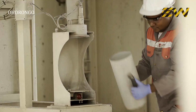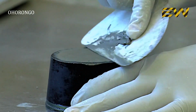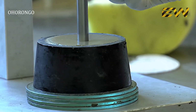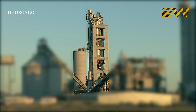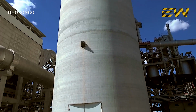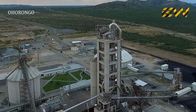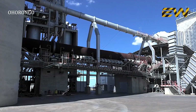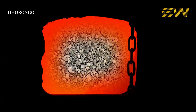The raw mix is tested once again to ensure that the chemical composition is correct in terms of the quality directives. Once the raw mix has passed the tests in the laboratory, it is conveyed to the preheater. The raw mill silo has a capacity to store 7,000 tons of raw mixture powder. Once the raw material has been processed in the preheater, it enters the 54 meters long rotary kiln, where the material is burnt to clinker at temperatures in excess of 1,450 degrees Celsius.